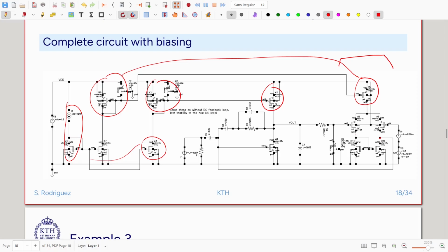I could have probably also taken it from this reference, but I have to be very careful when I reuse one diode connected reference for several points in my sequence, because it can result in instability.